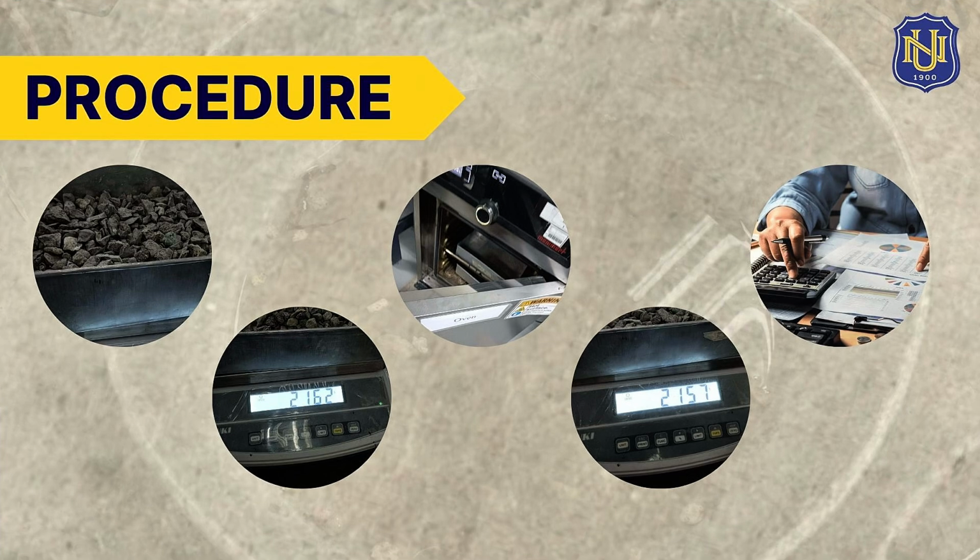First, prepare a minimum of 2,000 grams of coarse aggregate with a maximum size of 25 millimeters and 500 grams of fine aggregates. Second, weigh the prepared samples and record their initial weight as W1. Third, dry the samples inside an oven at 110 degrees Celsius for approximately 3 hours, or until a constant weight is achieved. After drying, allow the samples to cool. Fourth, weigh the dried samples and record the final dry weight as W2.